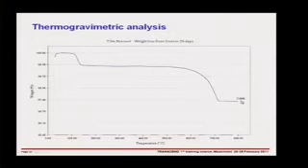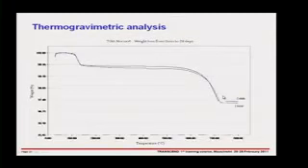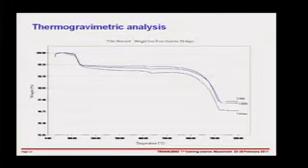Now, this is thermogravimetric analysis at just 2 minutes. So basically, we've hardly had any hydration, but we still get a small loss at around 100, which is the small amount of water that's already combined with the sample. And we get another loss here, which is a small amount of calcium hydroxide, probably present in the original sample. Sorry, I think that's not, this is calcite. So this would be a cement paste with a small amount of limestone in it, and this weight loss here is the decarbonation of that small amount of limestone. So you see it stays roughly constant through this scan.